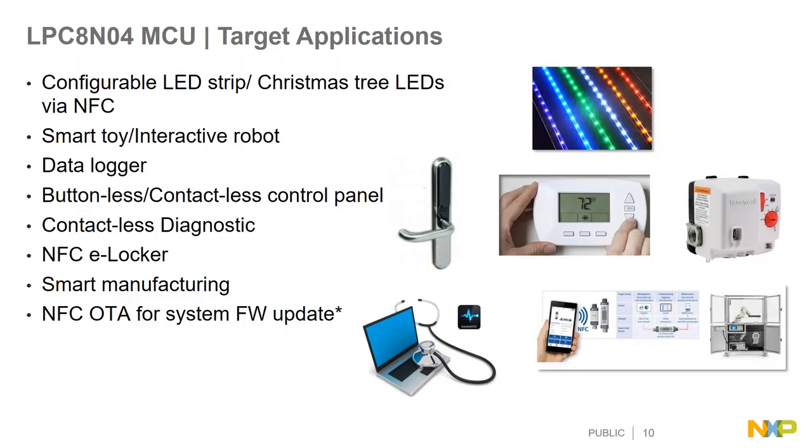Another key capability of this microcontroller is that we support over-the-air features for system firmware updates, and Tomas is going to spend a couple of minutes talking about that. We have OTA for system firmware updates, which means that with your cell phone or whatever you want to use to pair the microcontroller, you're going to be able to do firmware updates over the air, and this can be used in different applications all over the spectrum of industrial and consumer end applications. So we are not limited to these kind of applications. The sky is the limit. Anywhere you need NFC, anywhere you need co-processing or processing abilities with the Cortex-M0 Plus in a really power efficient way with energy harvesting capabilities included, the LPC804 is the way to do it.